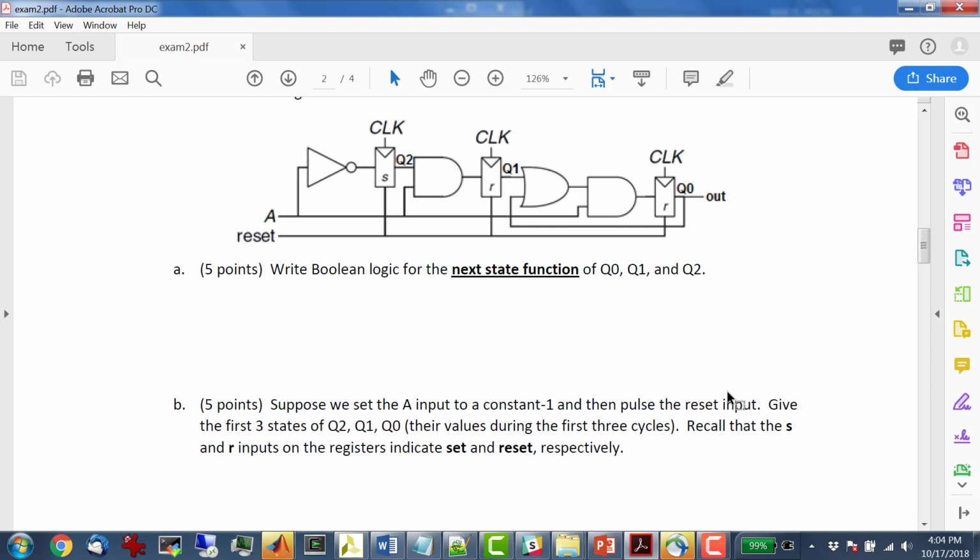And then in the next cycle, again, Q2 is locked in at 0 because it's not A, and A is hard-coded. Q1 is going to be Q2, which is 0. That automatically sets that to 0. And by the way, Q1 is kind of locked in now too, right? Oh, no, it's not. No, A is 1, so we're good. But well, it is because Q2 is not A, right? So this is equivalent to saying not A and A, right? So this guy, Q1, is going to stay at 0 from now on.